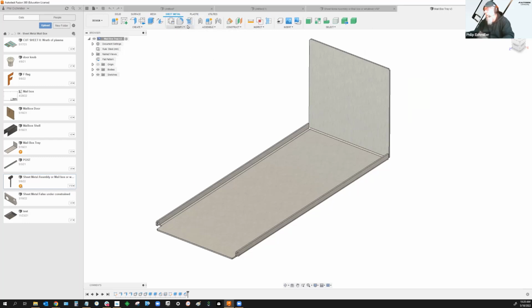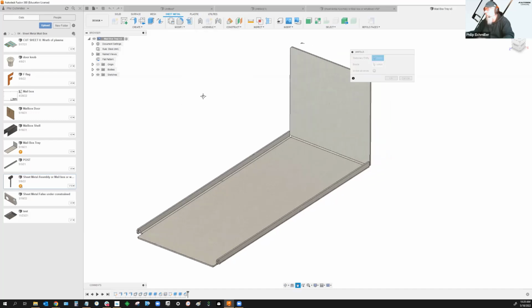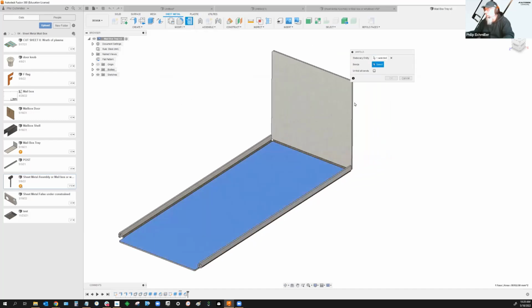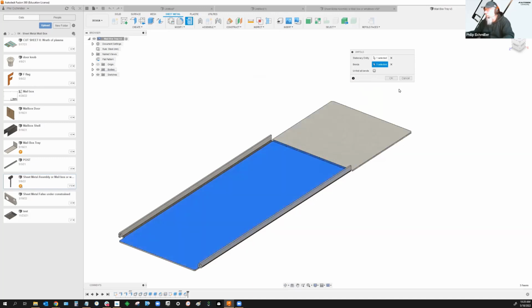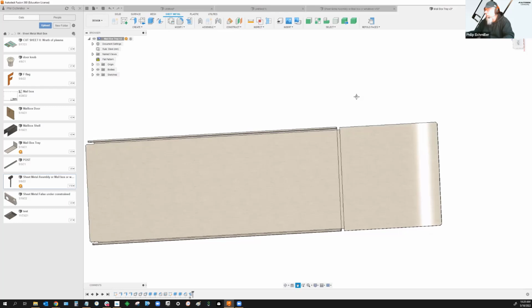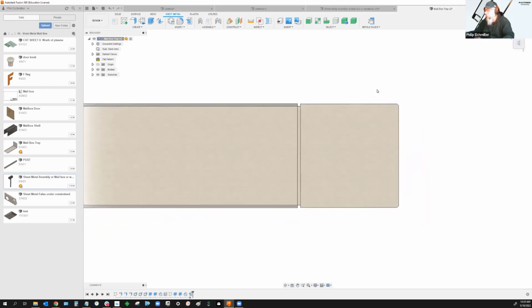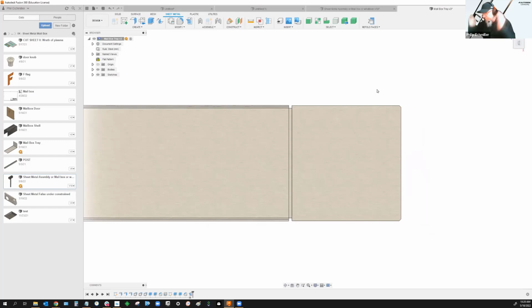So here's unfold. What unfold allows you to do is something pretty common in sheet metal, which is you need to model things based on how this is being fabricated. Sheet metal is one of those unique places where everything you're designing is built around how it's fabricated. Normally you might ask, is this 2-axis or 3-axis CNC? Is this injection molding? All of those questions are in your normal design process, but in sheet metal, you're like, this is going on a punch and I'm going to be using a 1/4 inch by 2 inch shear to make this slot. So that's the background on this.